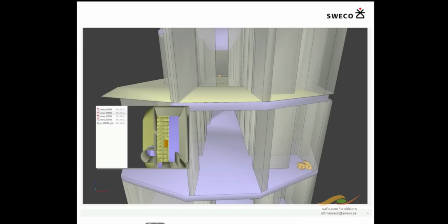To be very clear, Ulf, that QR stuff is a custom transformer that you guys have written. It's not part of FME, but the gods in Asgard have figured that out, so I guess that's something you've extended FME with. Yeah, that's true. It's fairly easy to make a transformer that writes a QR code, but it's a bit more complex to find them in a raster and use it like that. So that's when you need some form of custom format, a custom plugin. So this is a view where we have collected those results and display them through the 3D model.